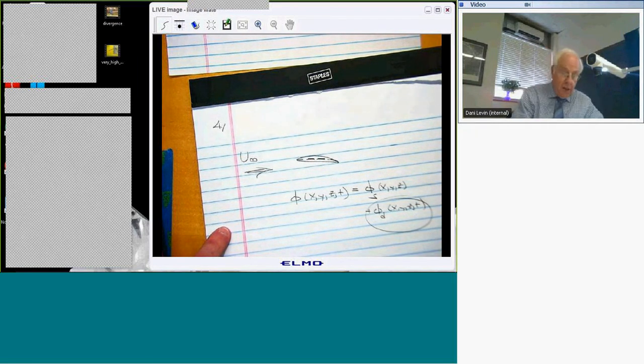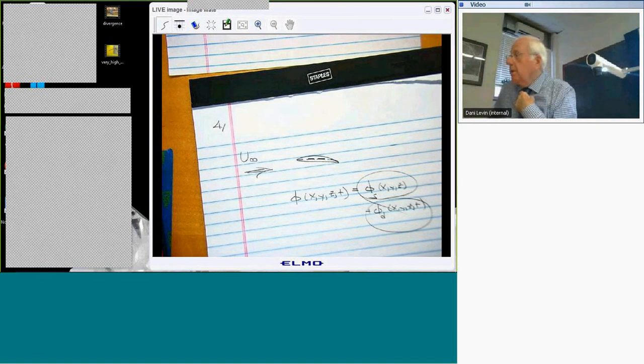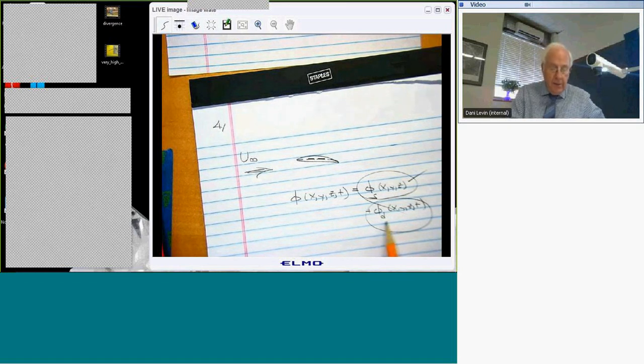The equation for the steady part will be nonlinear. And, you know, if you go out into the aerodynamics community, 90-some percent of the people out there are doing steady flows and have written code. So why should we bother to write another one? We know how to compute steady flows more readily than unsteady flows. So the thought is, I'll take a steady flow code, which is nonlinear in the context of potential flow theory, and use that, and then do a small perturbation associated with the dynamic part. And then I will end up with a linear equation for this.